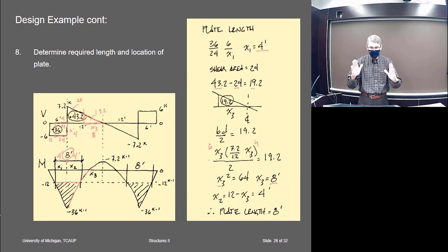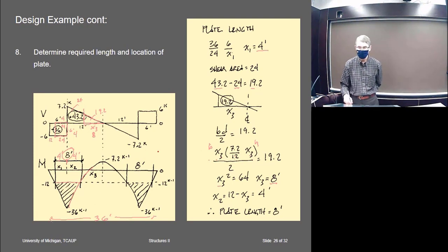But you can see you'd only need an 8-foot plate over each side, so that saves you whatever this total, what was this, 36, it was 36 feet total, right? And that was the total span of it, and you're only using 16 feet of steel plate, so you saved a good bit of steel plate, which is kind of the point.